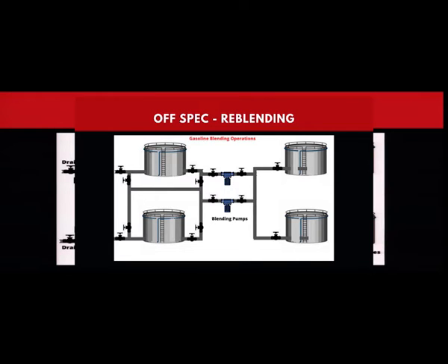It can be mixed with material of octane number 92 or 93, and then the final product can meet the expected specification. But the problem in reblending is effort and time. We have to put a lot of effort into the reblending, and once again the final sample needs to be tested in the lab. This is going to affect the steady state operation of a refinery unit.